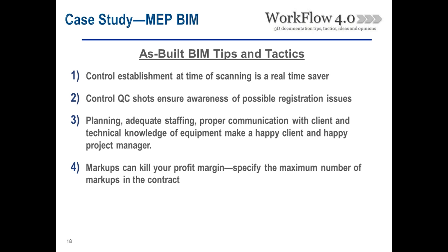The control shots ensure awareness of possible registration issues. Like I said, you always have to QC your clouds. Even though the registration comes out good, a visual inspection is paramount. Planning adequate staff and proper communication with the client, technical knowledge of equipment, make a happy client and a happy project manager. Again, planning. It's well worth the time spent to have a good game plan before you go out on site and have the people trained appropriately, or you can make a big mess out of a small project.